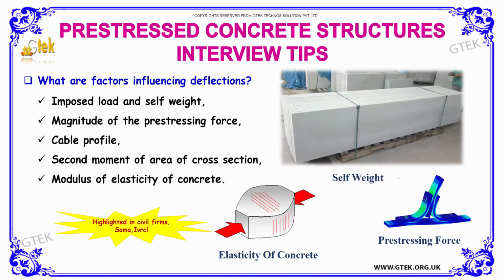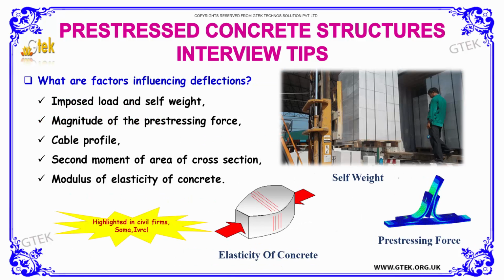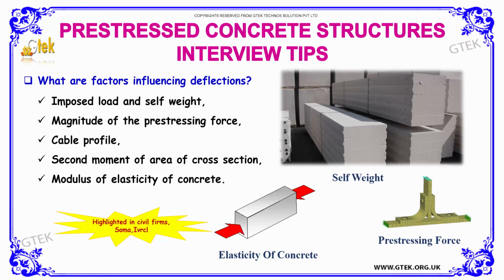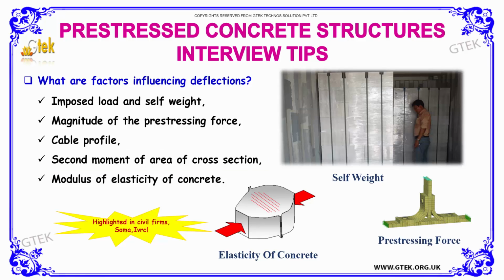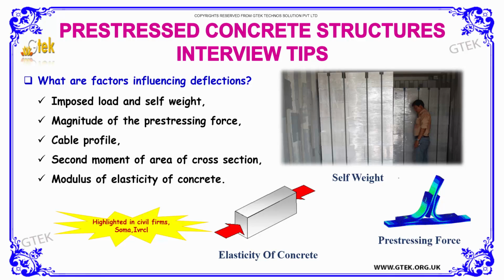So we got the next question. What are the factors influencing deflections? The factors influencing deflections are imposed load and self-weight, magnitude of the pre-stressing force, cable profile, second moment of area of cross-section, and the final one, modulus of elasticity of concrete.